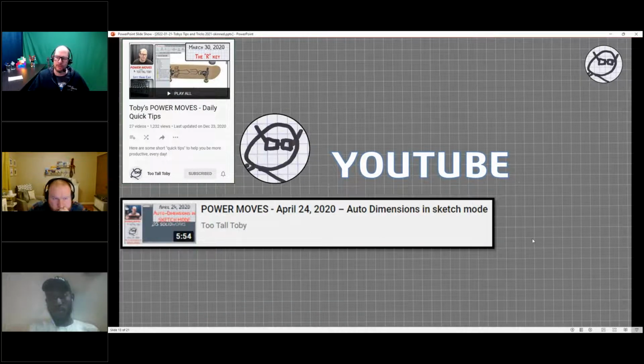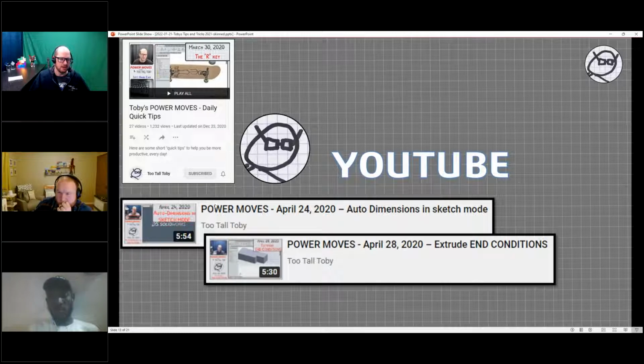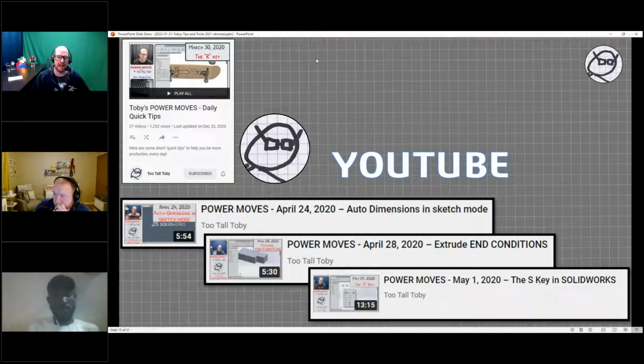Some of those other power moves that we talked about in the video today are things like auto dimension in sketch mode. I showed you how to type in the dimension value, and this video explains how to set that up and how to use it effectively. It also covers some of the end conditions that I used, like cut extrude and boss extrude, another great time saver. And how to use the S key in SolidWorks. One of my favorite commands in SolidWorks is the S key, and I've got a video on there that explains how to do that as well.